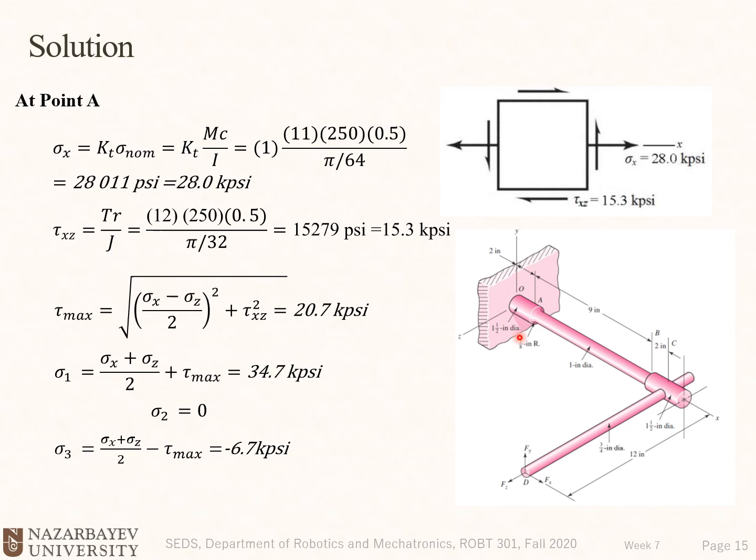In case, for example, we have a brittle material, you have to calculate Kt based on the radius of the fillet, and the appendix of the book specifically has the same beam with the fillet, so we could use this diameter here or bigger diameter or smaller diameter and the fillet radius to calculate Kt.